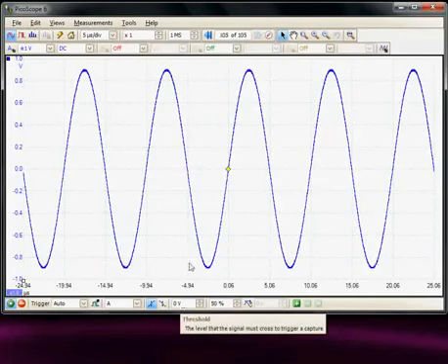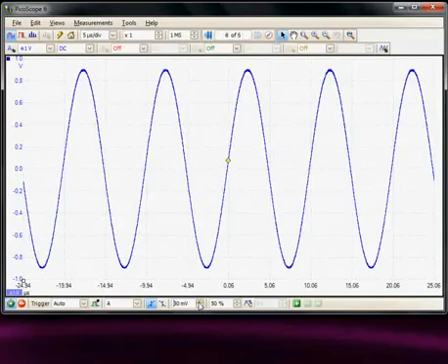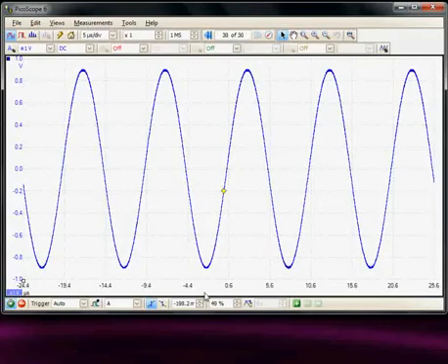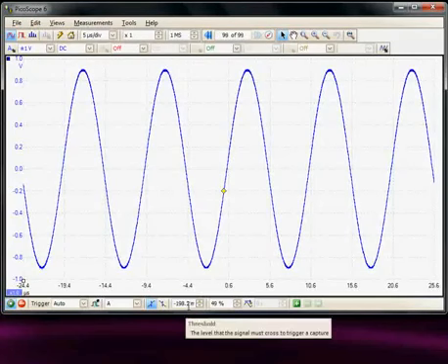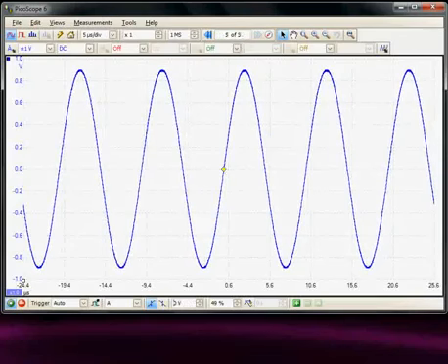This is the trigger level. So by default again it is on the 0 trigger level, and we could dial in any particular required level. So here I've selected 100 millivolts, and here we can see the trigger marker has moved up to plus 100 millivolts, and indeed we can just drag and position the trigger level, say at minus 200 millivolts with the mouse pointer. I'll return this to the center to 0, so we return the trigger level to the 0.